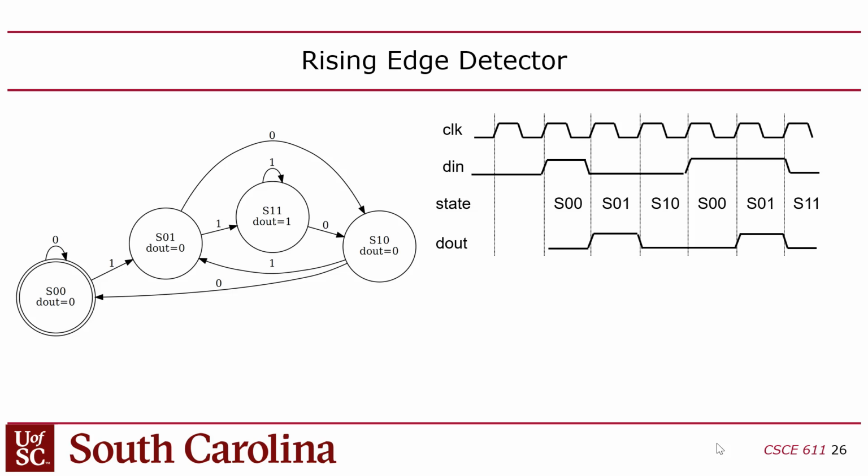right? So then you create the state diagram, and this one is fully populated with transitions. I don't have any don't cares in here. There's only 1 input, luckily, so I have 2 transitions coming in at each state. So if I'm in 0, 0, and I get a 0, I stay there.